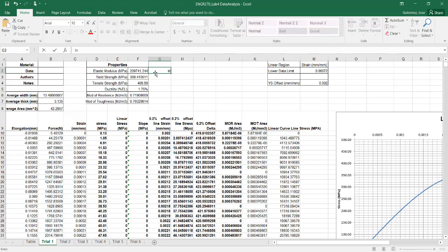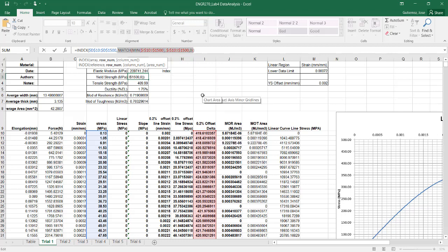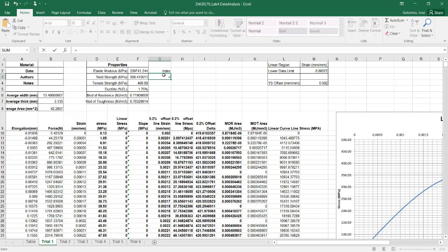So I'm going to add a cell that I'll call index. Let's borrow the formula since we've already typed most of it out. It's this match min, because we were searching for the number of the cell that was the minimum value from this delta. I'm going to press Escape after I've pressed Control C, and then type in that same formula. That gives me cell 233.